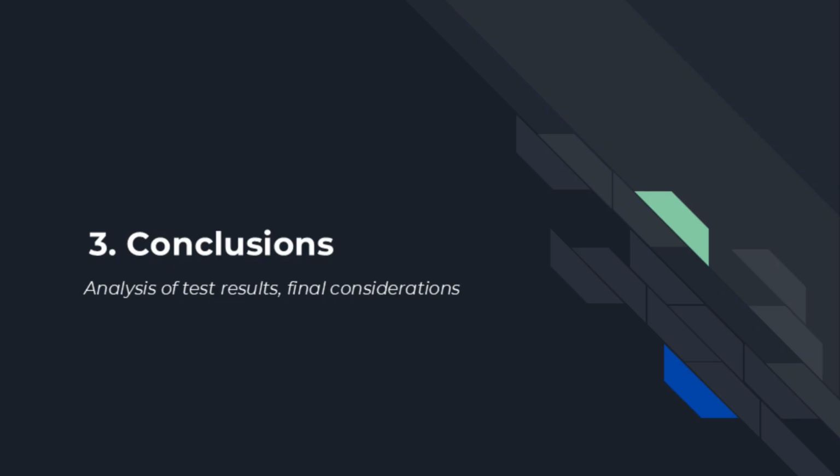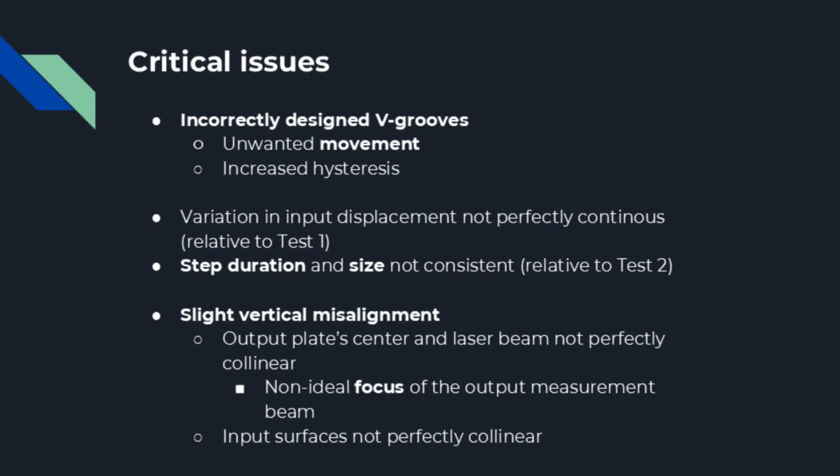In conclusion, our linear mechanical reduction system demonstrated promising behavior, but several issues emerged during testing. First, we observed a significant problem related to environmental vibrations. When 5 people were standing close to the experiment, their mere presence influenced the measurements, indicating a sensitivity to external disturbances. Additionally, the presence of people affected the ambient temperature and humidity, leading to unpredictable thermal expansions in the mechanism. This effect was further exacerbated by the non-kinematic design, making the system more susceptible to dimensional changes.